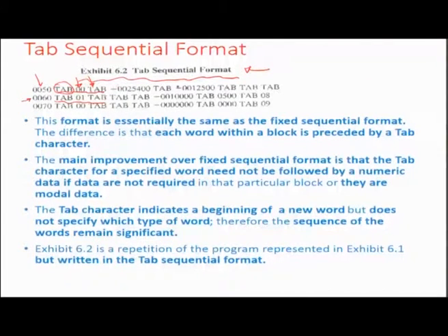keyboard, which takes you to the next level, that is the axis commands. So you have positioned yourself at plus 0025.400, plus 0012.500, and wherever there is no requirement, for example where the origin is there or 0 is there, or you don't need to change the entry, you just simply press 2 tabs so that it skips or bypasses the particular column and goes to the next step.